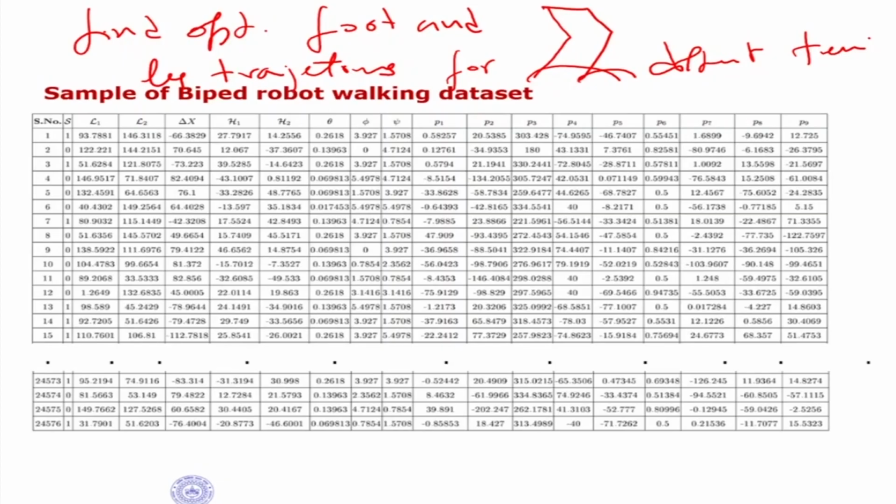For example, if I know that the robot is going up and there is an inclination in the upward direction, I start finding trajectories for different angles. So I take, say, 2 degrees, 4 degrees, 6 degrees, like that, and for each of these I find trajectories. If it is going down, again the same thing. Alpha is equal to each of these angles, find trajectories, and make a database like this. Now this takes a lot, because each optimization will take you minutes, if not hours, and to generate a database covering all kinds of terrain conditions will probably take you days.